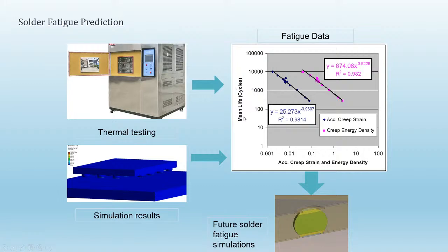So just to get the material fatigue data for a solder ball, we need to do simulation. Right? Without simulation, all you know is how many cycles it takes for a part to fail, and if you want to improve it, there's no feedback on what can be done to improve it quantitatively. You can qualitatively pick a better PCB, maybe a high reliability solder, but to establish this type of data, you need to have both simulation, which generates the x-axis, and the physical testing, which generates the y-axis.